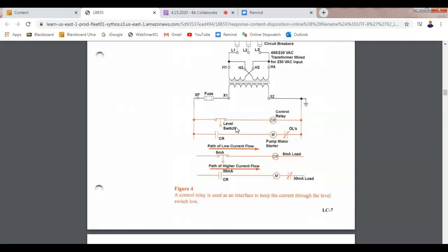So what we usually do is we take the solid state sensor and then we energize a control relay. Just about all your solid state sensors, every one that I've ever seen, has either one normally open contact, or it has a single pole double throw, and y'all understand those terms, right? So we can use it either normally open or normally closed. And if I need 10 contacts, what we need to do, of course, is take that and run it into a control relay, and then the control relay can bring in our other devices.